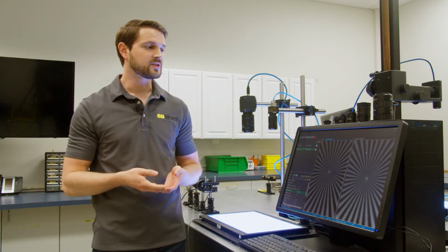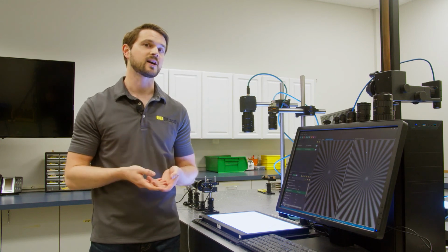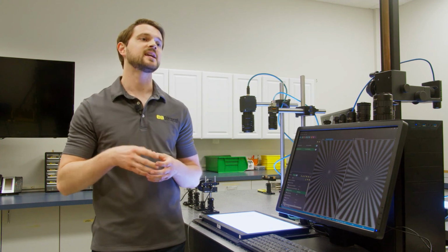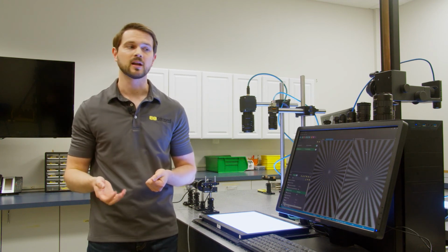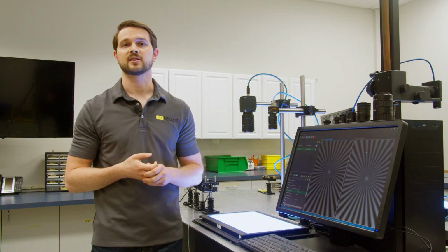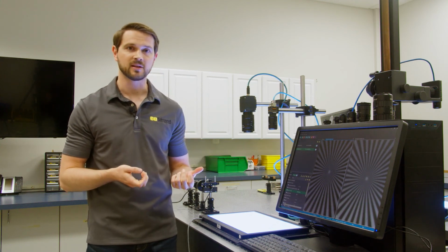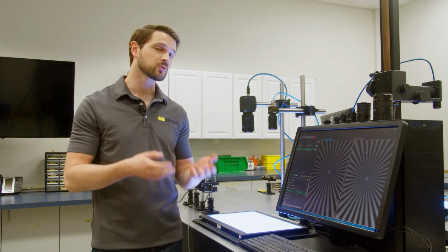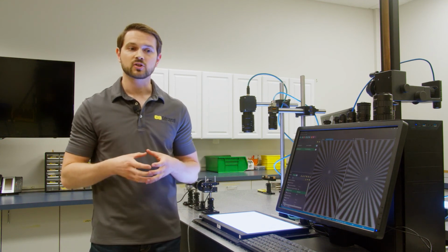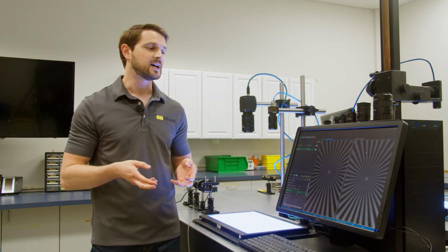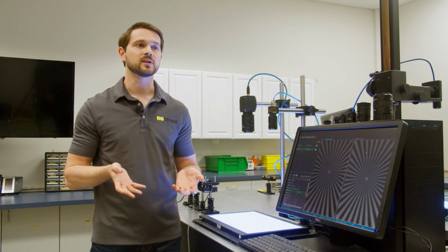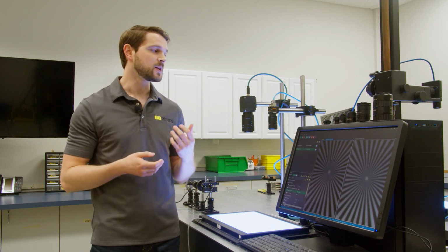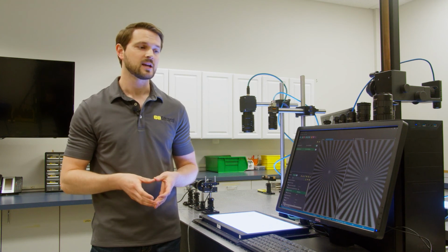This is something that's not often discussed: if you want to go to a higher megapixel count, blow up your image sensor. Generally speaking, if you blow up your image sensor, it tends to grow your pixel size with it as well. In this particular case, that's not necessarily happening, and honestly, in my opinion, this is the better thing to do in terms of maintaining and improving your image quality: making sure your pixels stay as large as they can. When you go to really, really small pixels, you can encounter signal-to-noise ratio issues and other things that you simply won't encounter with larger pixels.